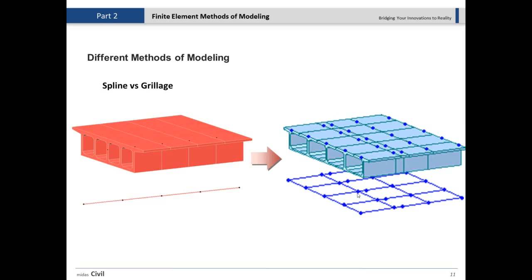And the transverse elements ensure that these separate girders right here are working as one unit, because in real life, they are not separate. We are just using these methods to simplify it and make it easier to do the analysis. But in real life, they are one part. Therefore, we are using these transverse elements. So these transverse elements do two actions. One, keep these main girders together, working as one unit and one system. And another action is giving additional torsional behavior, torsional stiffness.